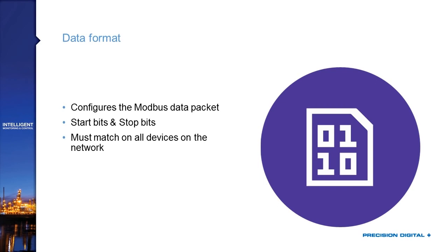And so long as all of your devices are properly matched, you don't really have to have a great grasp on what all of that means. All you need to know is that I have a device here that says that it's got one stop bit, so I need to make sure I've programmed all my devices to have one stop bit. And as long as you match all those data format values, then the system's going to operate just fine for you.